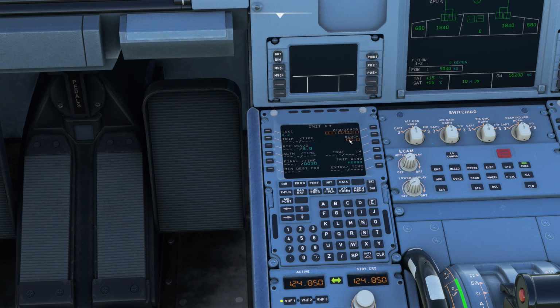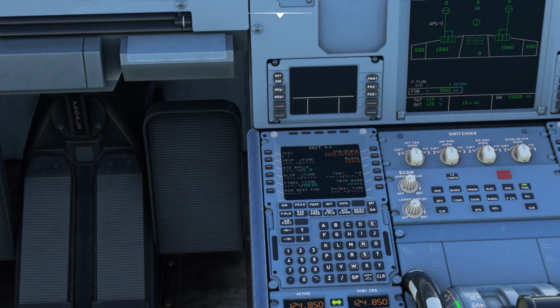So this is where we needed to remember the information that we had before. I've actually forgotten that information. I know it was 50 point something, so I'm just going to put in a random number. It's not too important at this stage. So I'm going to put 50.4, I think it was around there. And a slash again, exactly as it is there, with 30 being the centre of gravity. Okay, block fuel on board, so we had that before. The block fuel I've got on board is 5119. This time it needs to be entered as a point, so it's going to be 5.1.